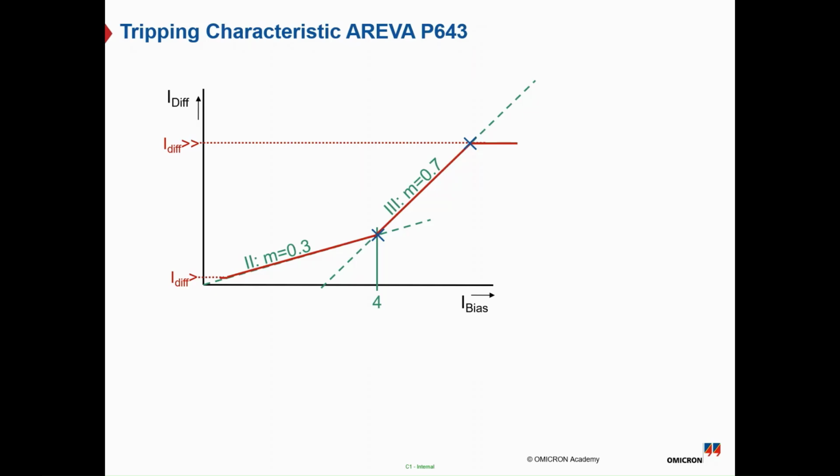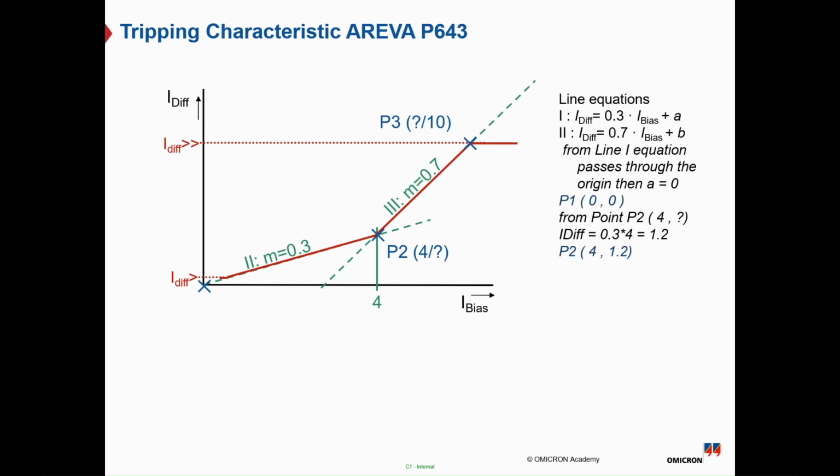And if you need to draw it step by step, you can define the intersection point for each point, point 1, point 2, point 3, and you can define it inside the relay file of the differential function. And we can see this in the practical demo part 2, inshallah. So to represent this dual slope characteristic, we will have 3 points. As you can see, point 1 is 0, 0, because slope 1 is starting from the origin.